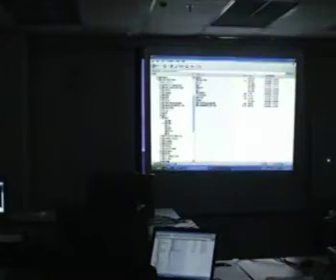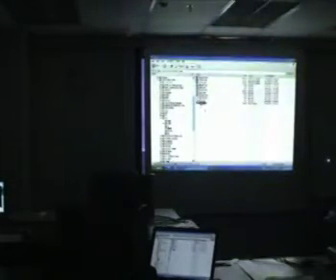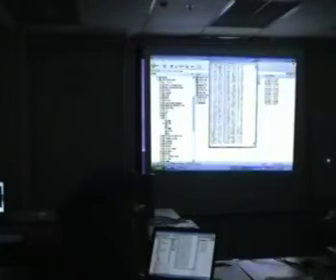Okay, so now we've got a report file. I'm just going to go to Windows Explorer to show you the file which has been created, points.txt. You can see this is what it looks like. We've got our X column, our Y column, and this is the string column. This is for Land Desktop also. Yes, Land Desktop also.